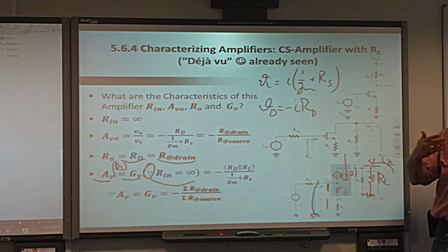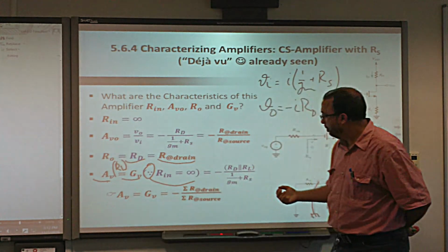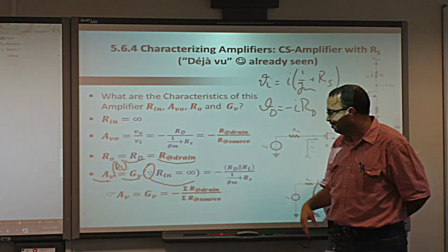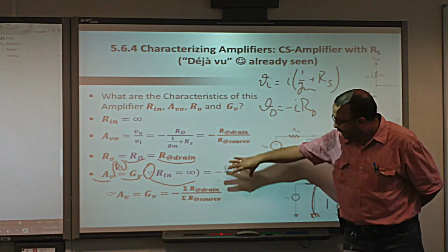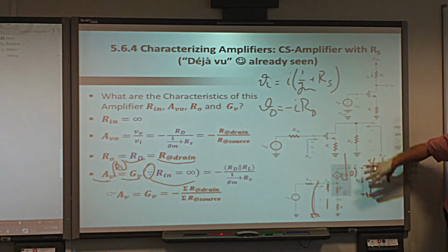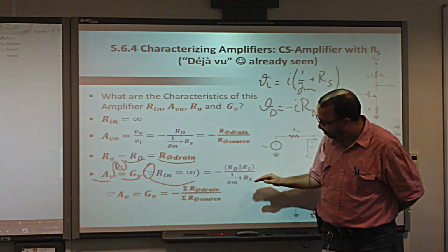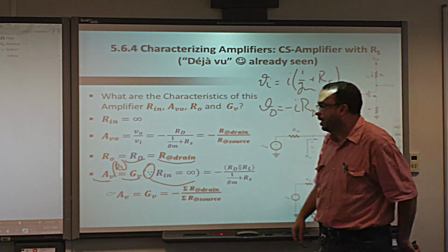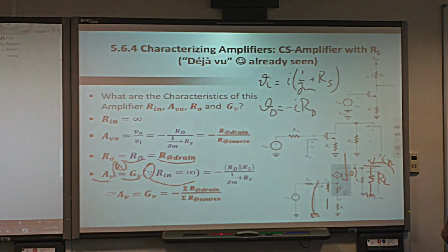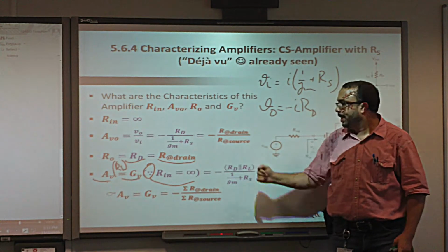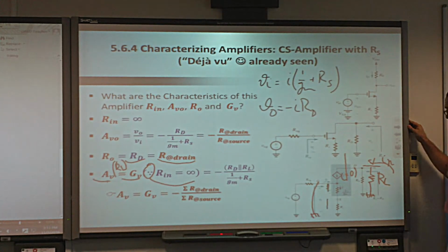Right? In 2 minutes, we finish. That's why it took time, because I have to explain. But later on, it will be like that. Very good. You can see also, again here, the same story, although there is a minus. It's actually the total resistance at the drain, RL parallel RD, divided by the total resistance at the source. Same exact observation that we had before. So the voltage gain, now we can express it just as a ratio of resistances. This is the beauty of electrical engineering.